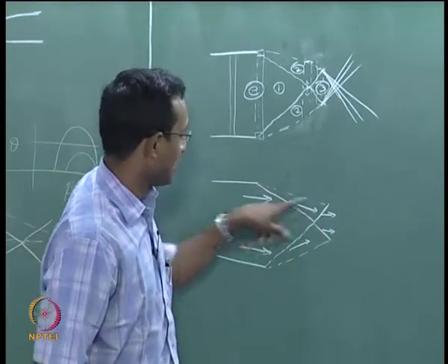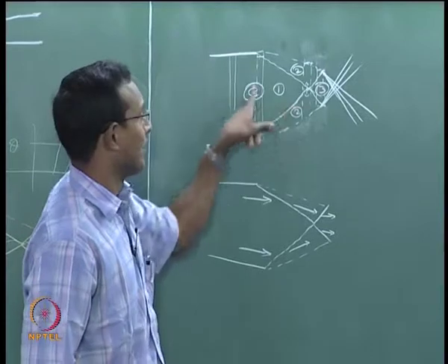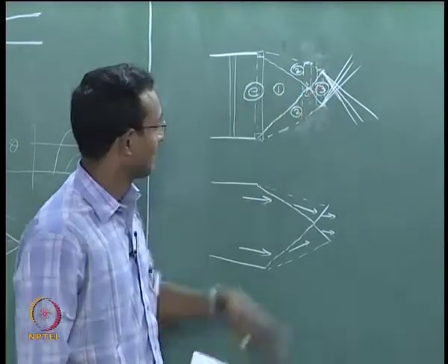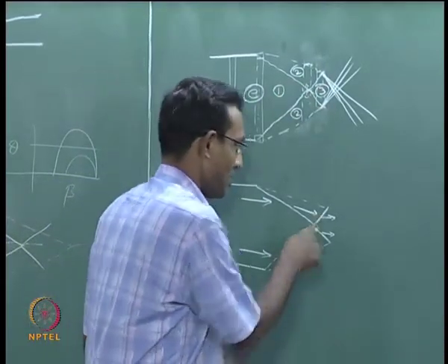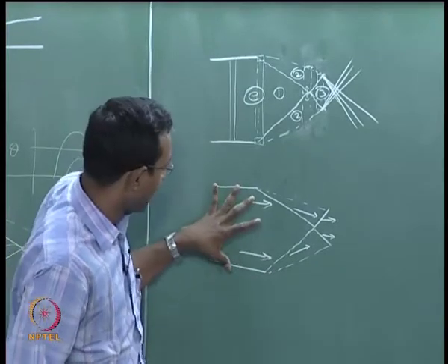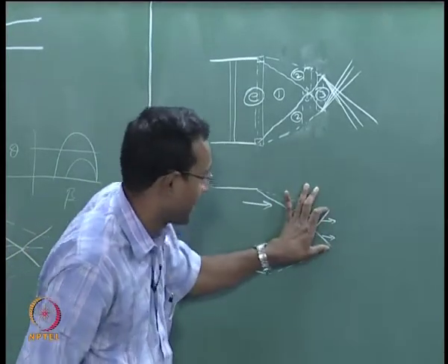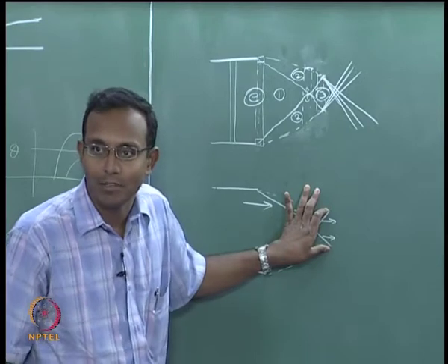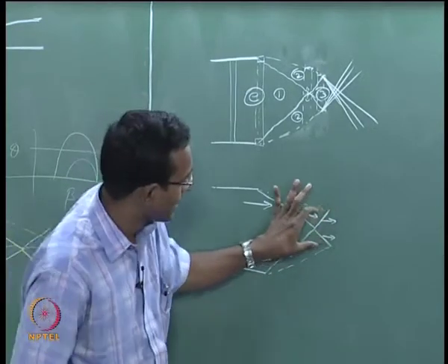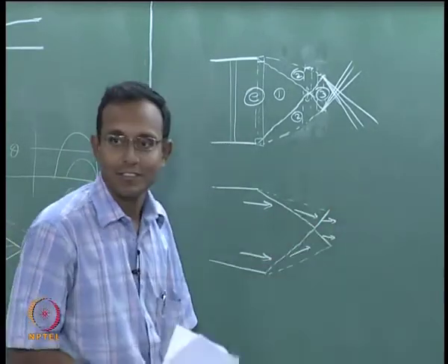I am drawing the velocity vector here and I am showing you the region plot and the pressures I am describing here. Flow velocities are parallel. It is as if this jet has been shrunk to a smaller size jet here. I have come up to that point. The jet has become a smaller size jet and they are going parallel out like this.